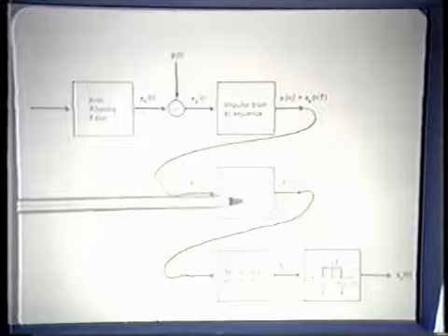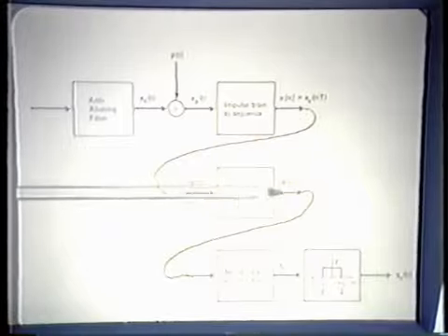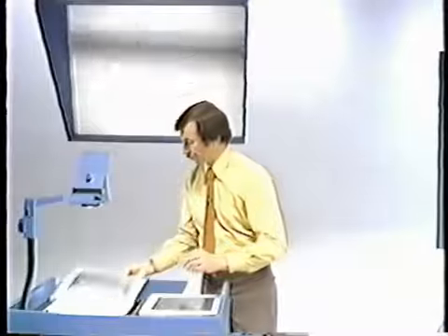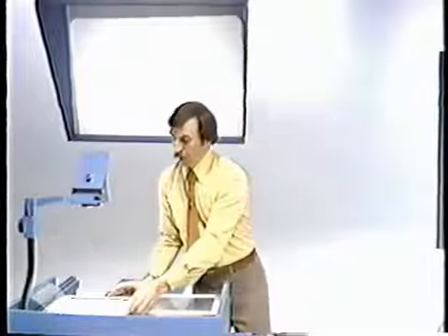Okay, now at that point, where we are in the system is at this point, so that we've converted to a sequence. We now want to carry out some filtering, and then after that filtering, convert back to a continuous time signal. All right, so here we are at the spectrum associated with the sequence. And now the processing that we're carrying out is linear time invariant filtering in the discrete time domain. And what that corresponds to is multiplying this spectrum by the filter frequency response.